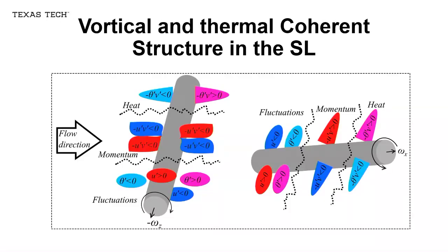It's primarily coming from the alignment of the vertical structure. So in a typical flat wall, homogeneous flow, you find that the Reynolds shear stress is equal to the heat flux. But when the structure is actually spanwise aligned, not in the streamwise direction, then these two are quite different from each other. So it is that inhomogeneity, and the difference in heat flux and Reynolds shear stress, is mostly due to how the vertical structures align in the flow.